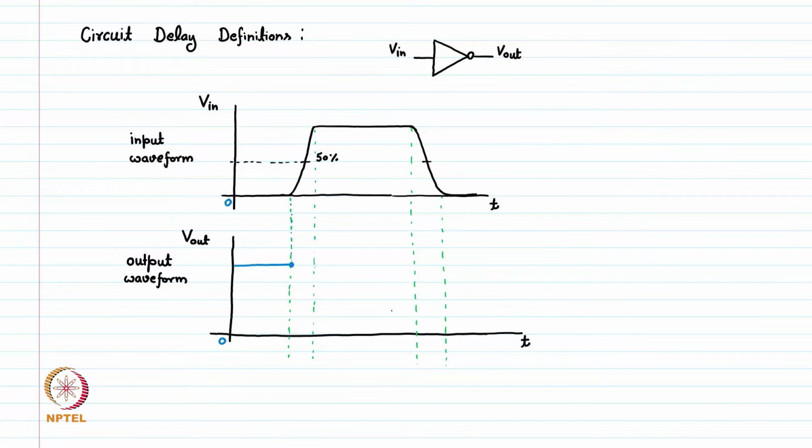However, as we change the input, the devices PMOS and NMOS do not immediately respond to this change. There is an inherent delay in the devices; for example, turning on the device takes a certain amount of time. The charge carriers need a certain amount of time to respond.